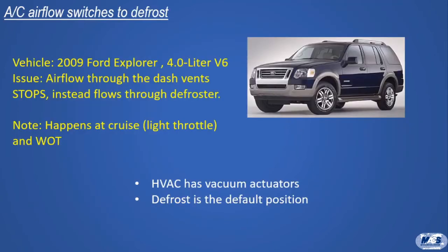AC airflow switches to defrost. Sort of obvious. The symptom made the problem area very apparent. As the 2009 Ford Explorer XLT with the 4.0-liter six-cylinder was cruising down the road, with the manual air conditioning on, the airflow through the AC registers would stop and switch to the defrost outlet.